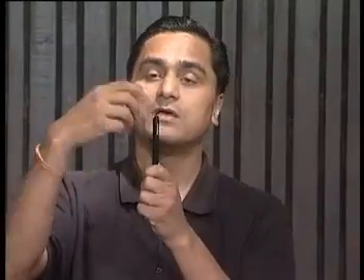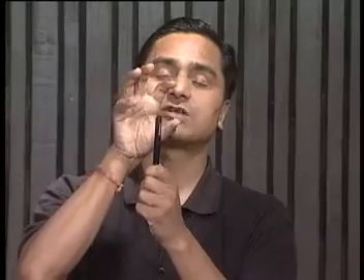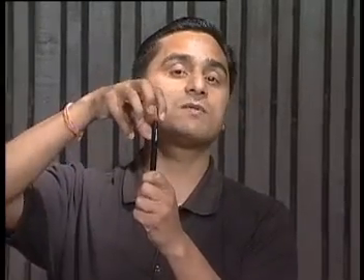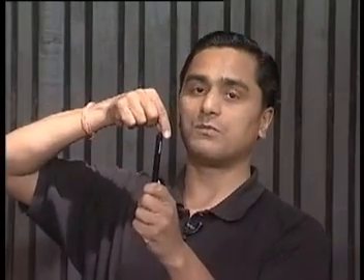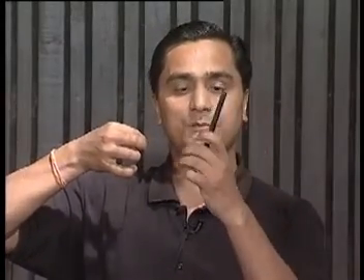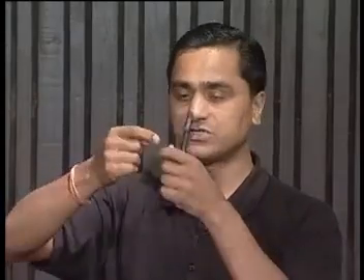But once the laser travels into the prism, the refractive index is different here, and we need to apply a correction for this. If the prism were not there, the laser would have come here and then gone back. So basically I should measure from this point, not from this point, but my rod says this is the point. This difference is K2, the other constant.